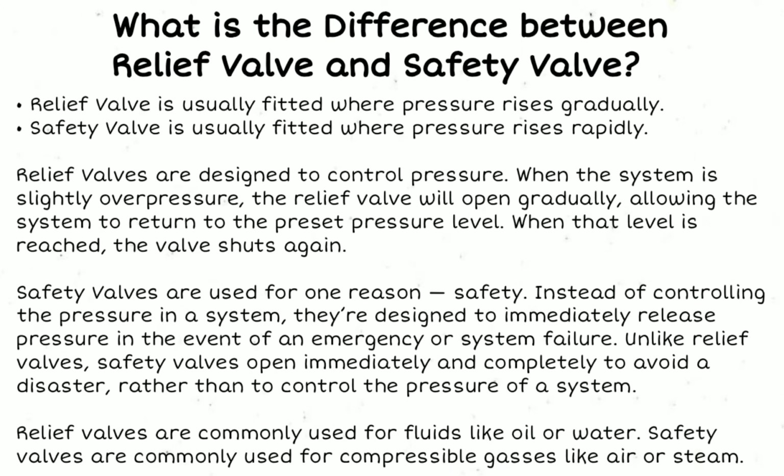What is the difference between relief valve and safety valve? Relief valve is usually fitted where pressure rises gradually, while safety valve is usually fitted where pressure rises rapidly. Relief valves are designed to control pressure. When the system is slightly over pressure, the relief valve will open gradually, allowing the system to return to the preset pressure level. When that level is reached, the valve shuts again.